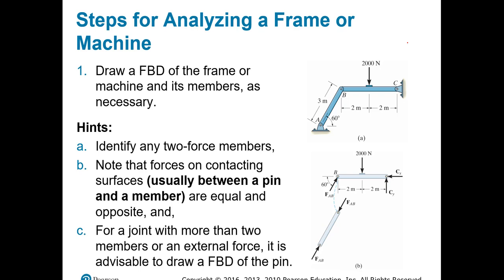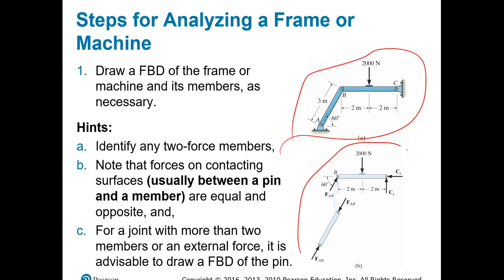So when you have a system like this one, if you want to break it up into two parts, the same rules will apply as we've been discussing. You can break it up, no problem, but don't forget the internal forces that are related to it. That's the most important thing with this. And if you want to get rid of the supports, as was taught throughout your chapter, don't forget to add the reactions that are connected to that.